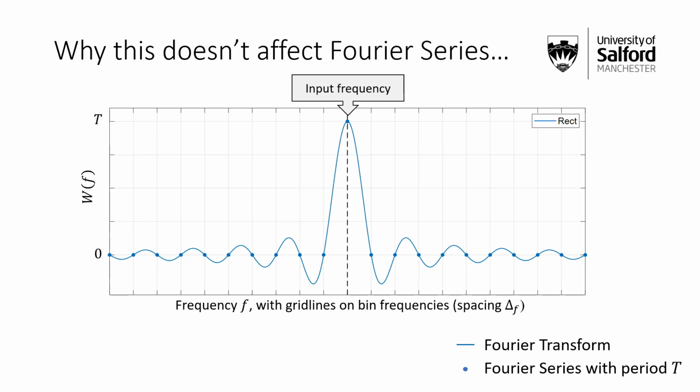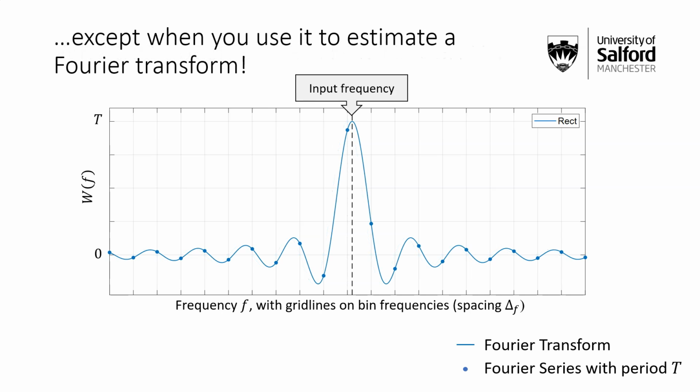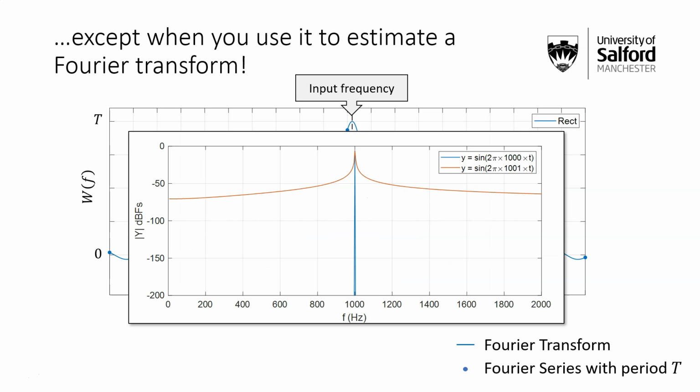But what about when we move the input frequency slightly to the right? Well, what we're going to get then is this, and suddenly it's all a lot more visible. Suddenly, if you put in a frequency that doesn't match one of the harmonic frequencies of the Fourier series, it can see this smudging. And you can see that we're getting lots and lots of non-zero values coming up in the output of the Fourier series. They're attenuating away from the peak frequency, but they're still definitely there. And that is the reason for this smudging that we saw on this graph.